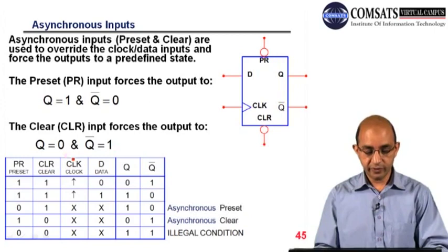If you look at this characteristic table, whenever we have preset 0, irrespective of the clock and D, we will set the latch. This is unavoidable.